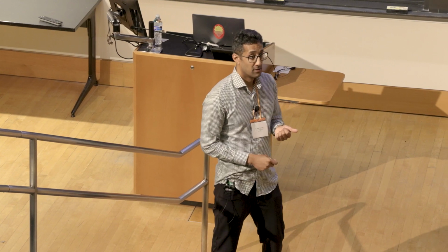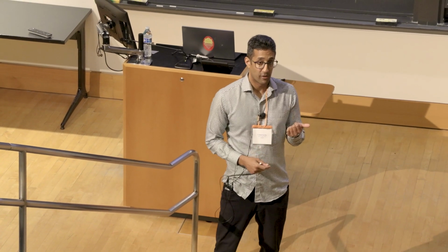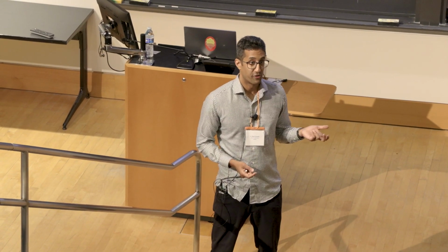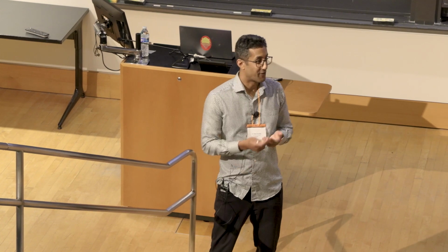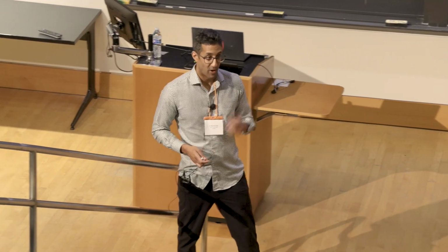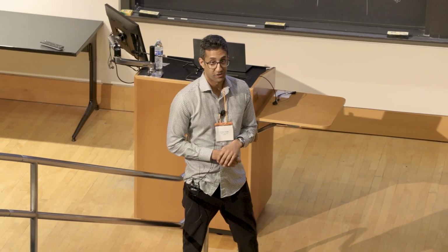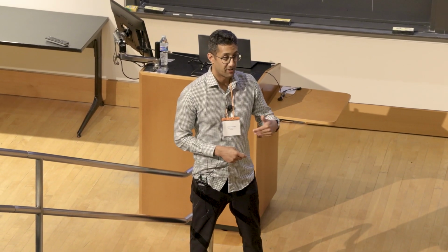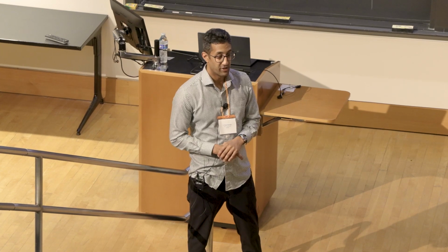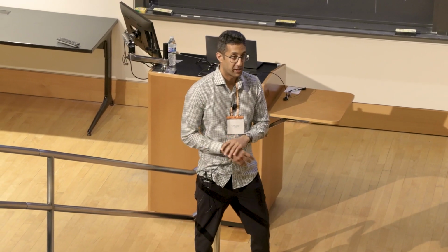Second thing is, you can never build a model for 200 components or 250 components. That'll take forever. One model, typically for one fuel component, might take 1.5, 2 years to build, with the kinetic models, then to do all the experiments to validate that. So you need a palette. We call this a surrogate palette.